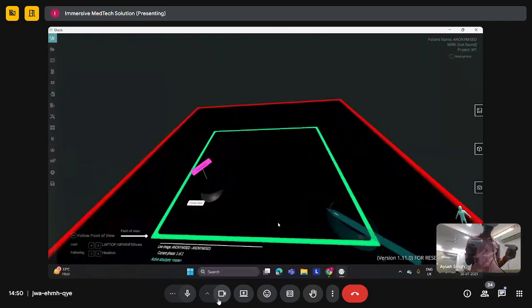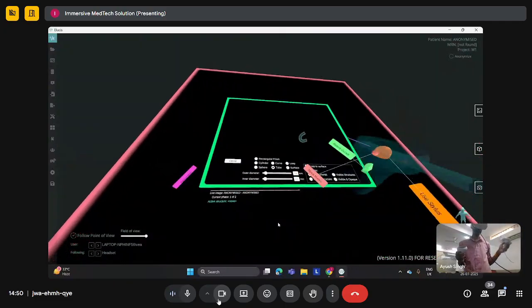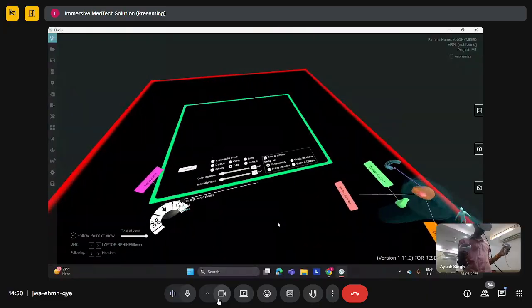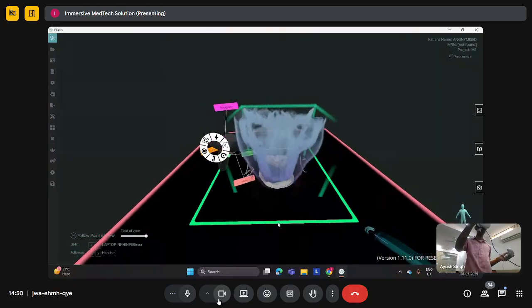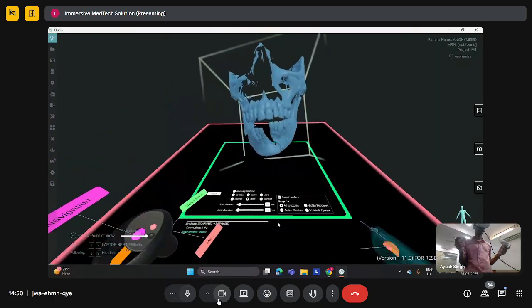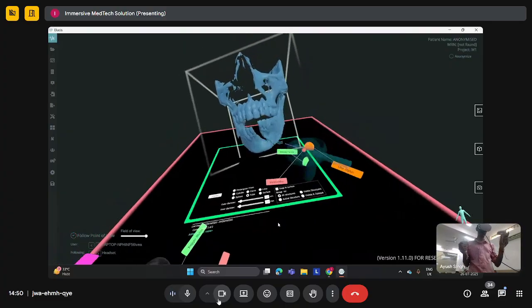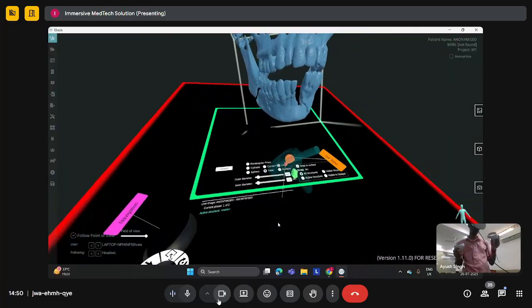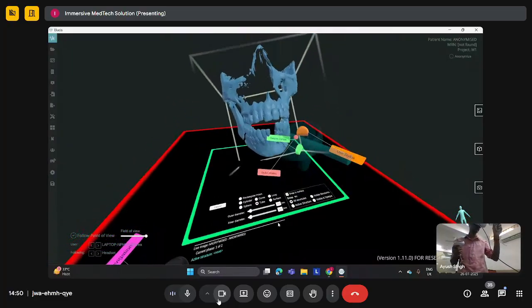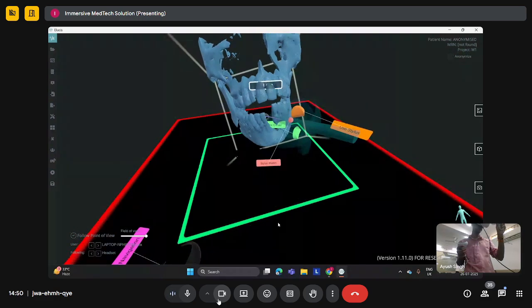I deleted this particular part. So this means we can design any sort of surface that we require and have our particular structure creation directly. Now, bringing back over here and showing how we can build connectors between these points. What we can do is click on the small tubular structure and then select the points that we require.